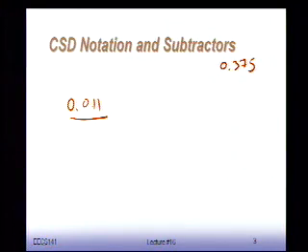If we basically say we have somewhere a binary point. Now let's go a little bit more generic. Suppose I have something like this. That would be my coefficients. Now remember, for the add shift approach, zeros are cheap, right? You don't have to do anything. Every one is going to cost you an addition, because every time I have a 1, I have to do a shift and an add.